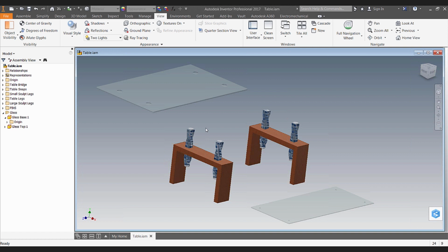If you look at Inventor's Content Center, this idea of a predefined library that has bolts and things like that, they actually design iMate elements into a lot of those components. Obviously, with bolts, the design intent is that it's going to be inserted into a hole or an extrusion or a void, and there are other things that are going to be connected onto it.